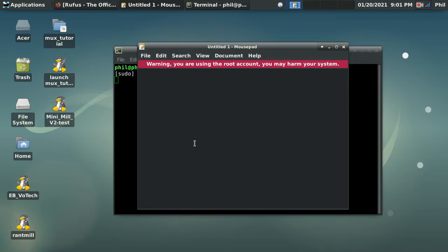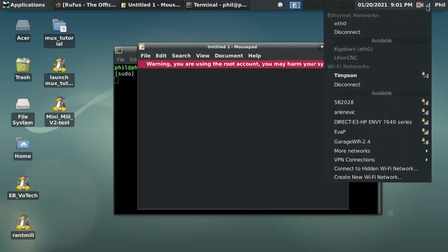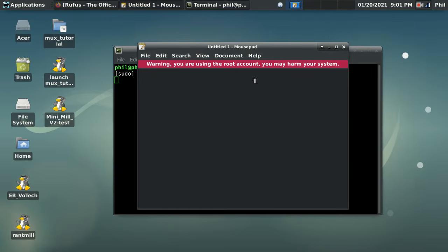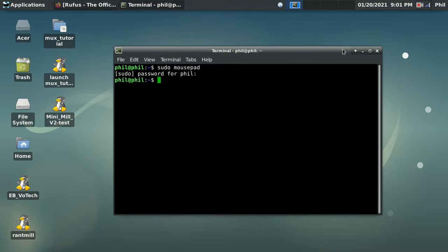There are times where you're going to have to go in and make subtle changes to certain files, like in the case of the network manager, to register a Mesa 7i76 on certain distributions of Linux. You have to go in and just change a commented out section of the network manager in order to use the wired connection within the network manager. It's not as hard as you think.